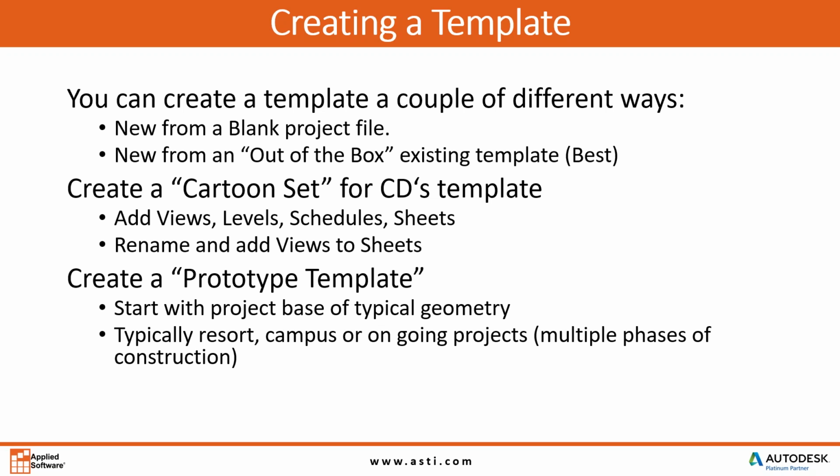You can create a template that has a basic set of CDs where you add your levels, views, schedules, and sheets, and you rename them accordingly to the proper structure, following your current in-house standards, and then you apply all those views to the sheets, and it's all blank. So when a project gets started, you just start with this template, you save as, give it the project name, and then you start laying out your designs.